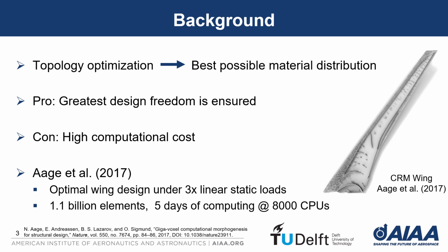Therefore, a design domain discretized with 3D elements is generally used as an initial design for topology optimization. During the optimization, the elements which do not contribute to the stiffening of the structure are removed. In this way, the greatest design freedom is ensured, but at a very high computational cost.